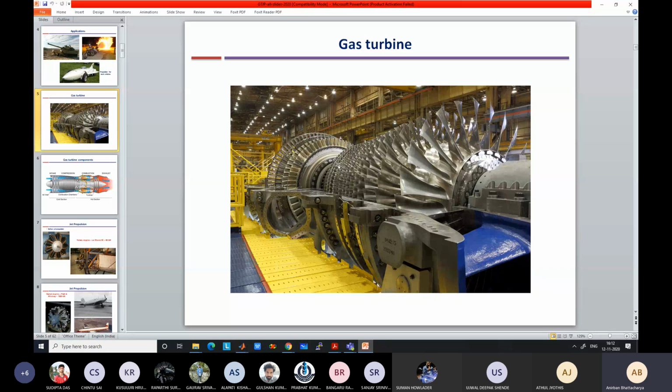Density will increase. Because the mass flow rate is constant, the annular area through which the gas is flowing has to decrease, so the length of the blades keeps on decreasing. So if you have a single shaft and a very large number of stages mounted on it, what is the problem?